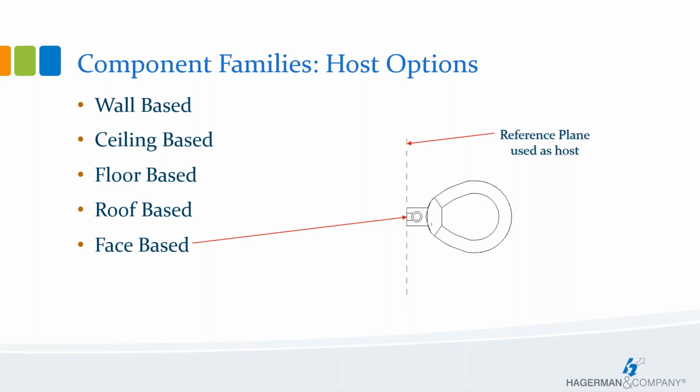We also have ceiling-based elements, commonly used for lighting fixtures and air terminals. We see a lot of floor-based elements for various types of furniture and equipment, especially if the element will be cutting a void out of the host. You will need to use one of these templates. Now, a lot of the time, users will find it a little too restrictive because that means you can only host to those elements and nothing else.